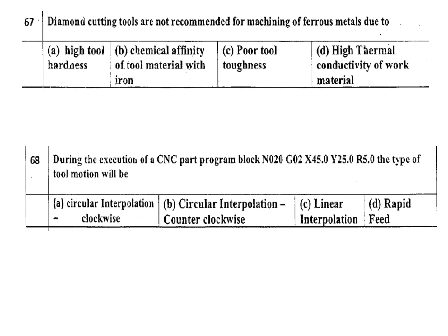This is the ISRO question paper from 2006 to 16, Production part 8. Question: Diamond cutting tools are not recommended for machining of ferrous metals due to A. High tool hardness, B. Chemical affinity of tool material with iron, C. Poor tool toughness, D. High thermal conductivity of work metal. Its answer is B. Here, carbon of diamond